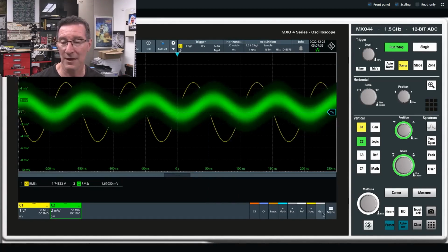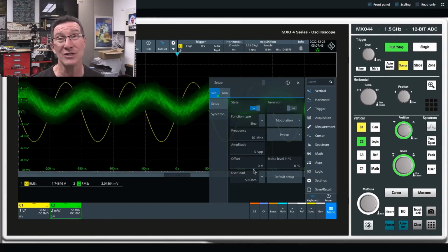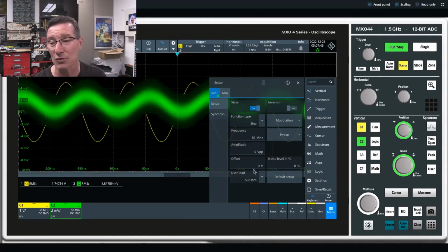But before we go ahead with that, I'll just mention the signal gen here. You want this to be as high an amplitude as possible, because the output signal that you're actually trying to measure, that common mode signal, is really low. So the higher the input signal, the better. So I've gone up to the maximum amplitude here of 5 volts peak to peak, and we've got a frequency of 10 megahertz, because that's a typical figure in the data sheet, which we want to try and verify.